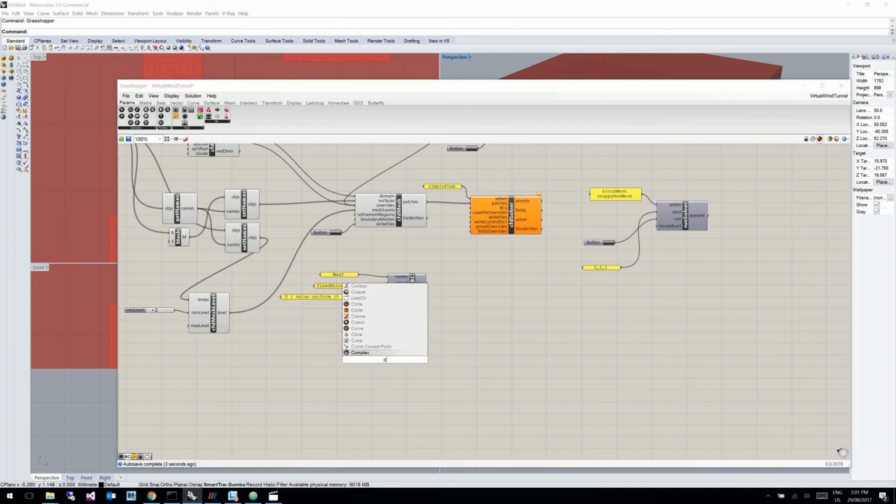We want to add another boundary condition for the outlet condition on the min-y. So this is min-y. In this case, we just want to use fixed pressure. The default definition for fixed pressure is a fixed pressure of 0, which is fine in this case. We don't need to override it with any special values.